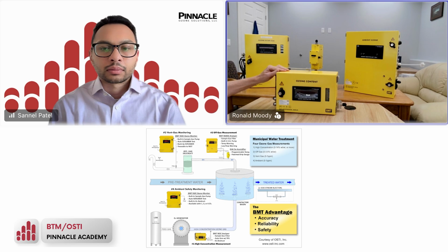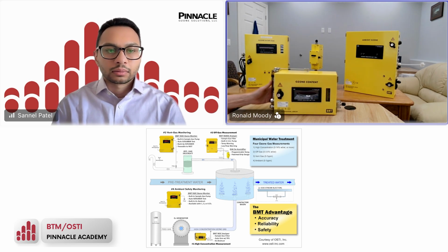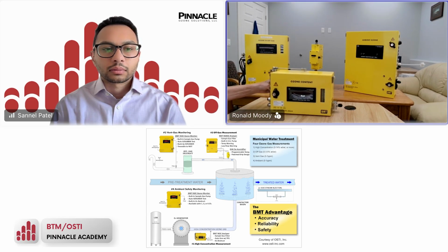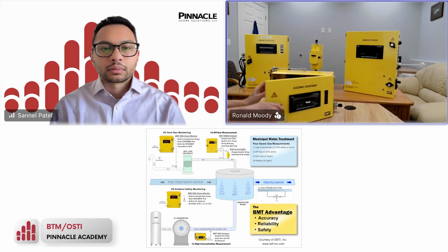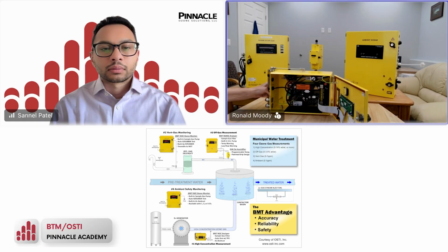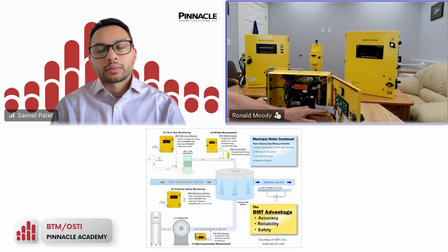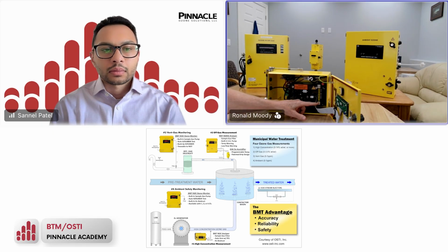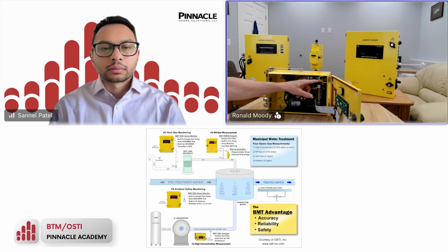Usually the pressure from the process is enough to move ozone through the analyzer to where a small sample is made and then destroyed with a catalyst destruct at the end. So this one, high concentration analyzers don't require sample gas pumps. Here, just a quick view on the inside, you see the ozone comes in, and it's a small amount of ozone, usually 3 to 5 liters per minute. And we can throttle back the pressure here internally with this flow meter. It's measured and throttled back here to that level.